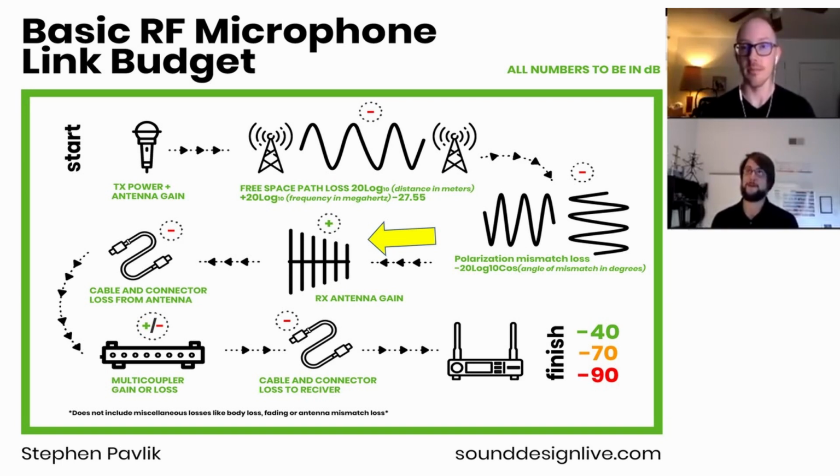It can happen. We don't need to dive into that, but okay, we're pretty much always going to have positive gain from an antenna, and that's passive gain, as we've talked about with antenna patterns. I'll use this as an example again. This is going to be basically our cardioid. Because we're not radiating in this direction right behind it, that radiation is forced forward. And so that is our passive gain, which is about 7 dBi. So at that point, we can use this little green plus here to add 7 to our link budget.